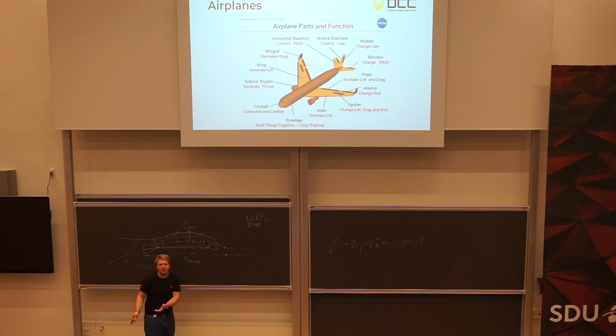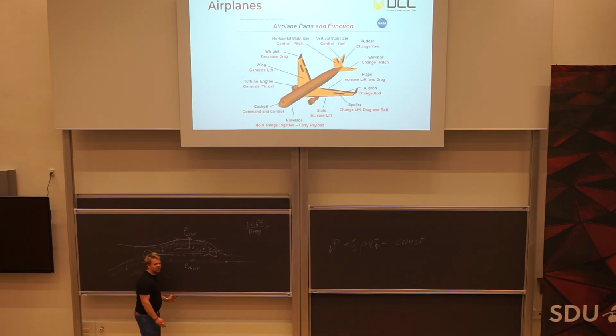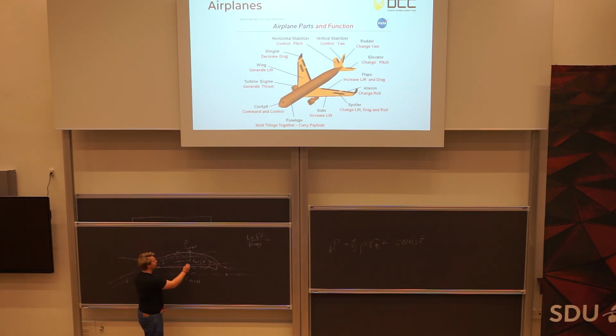So for takeoffs and landings, we would use them, but not in cruise. Then you can also have something amazing, which is called a spoiler. It depends on how you build them, but usually it's just a wall that extends from the wing and totally disturbs all airflow around it, makes crazy airflow all around, and you lose a lot of lift and increase drag drastically.